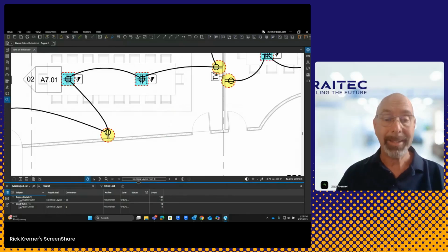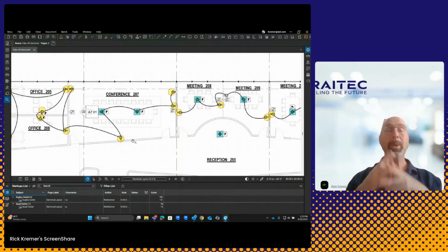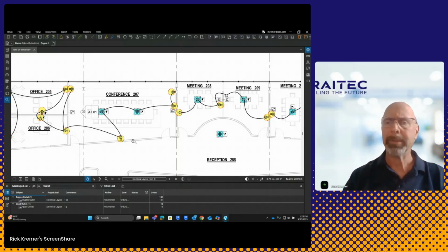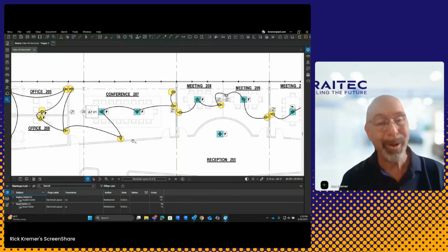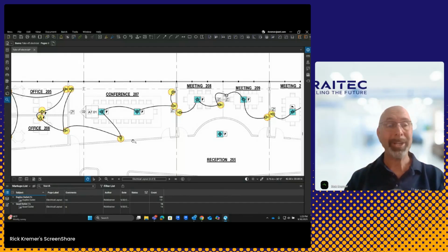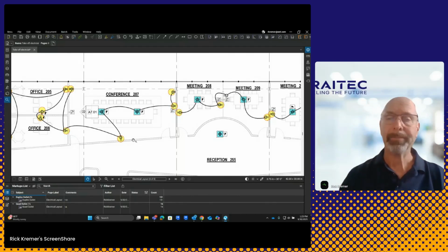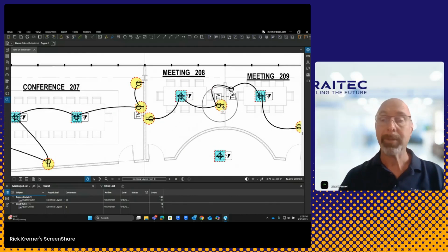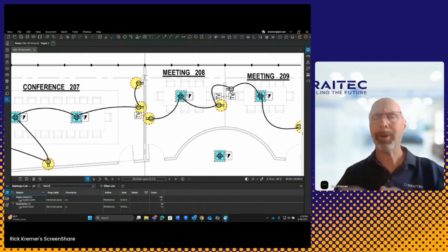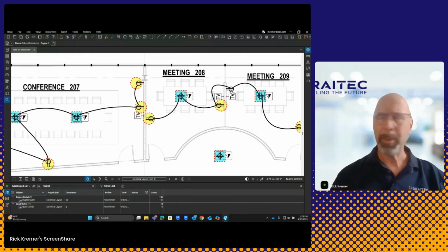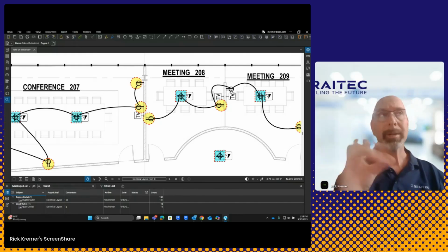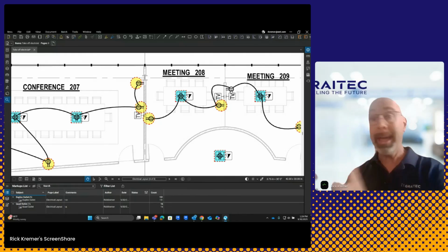Let's take it yet to the next level. Counting is fun. We can start to apply a count measurement, but you'll notice sometimes Bluebeam Review doesn't catch them all. Remember, it's just a computer application. You still need your eyeballs on the drawing over here to verify that information. Right now, I just noticed that the duplex over here missed one. In reality, folks, this is going to happen. When you start to scan your drawings, it might miss some of the objects. Remember, it's looking for an object, not something that has, let's say, AEC information or a parameter or type information.